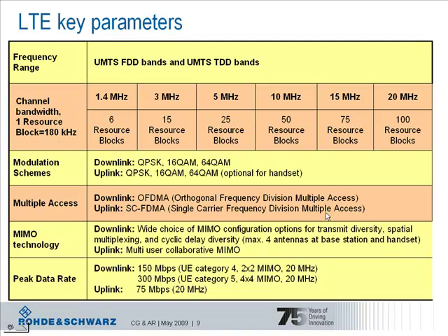The channel bandwidths for LTE. There are bandwidths defined: 1.4 MHz, 3 MHz, 5 MHz, 10 MHz, 15 MHz and 20 MHz. And each bandwidth is composed of a certain number of resource blocks. As you can see in this table, a resource block is defined to be 180 kHz each, and the resource block represents the smallest entity for a resource assignment. So a terminal or subscriber can be assigned one resource block or multiples of it. And this is true for uplink and downlink. So 1.4 MHz is represented by 6 resource blocks, and so on up to the 20 MHz being represented by 100 resource blocks.